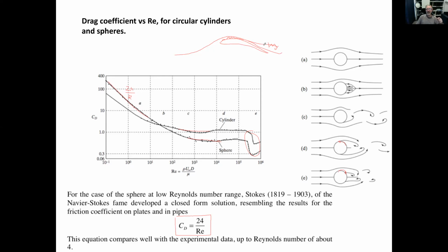On the other hand, that's not a good idea, because when you want the flow to be laminar for less drag, you're going to lose. So I always say that vortex generators on an airplane wing are an afterthought, and they are a result of really not doing a very good design the first time. Anyway, that's just a remark.